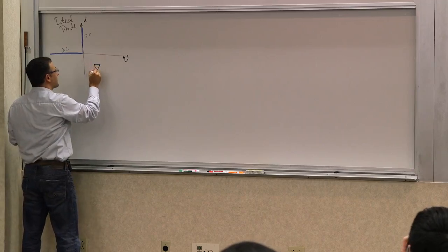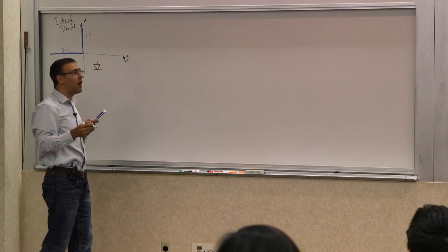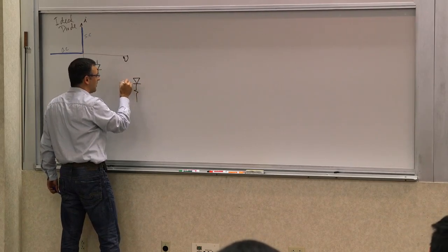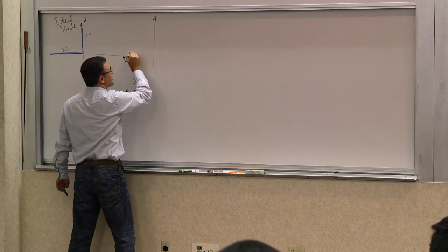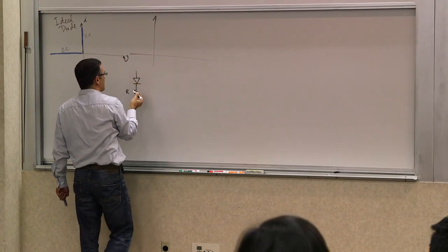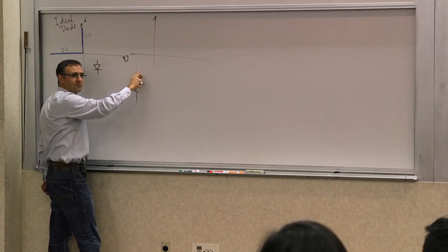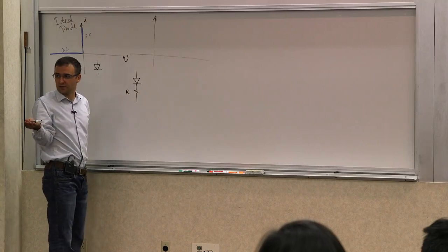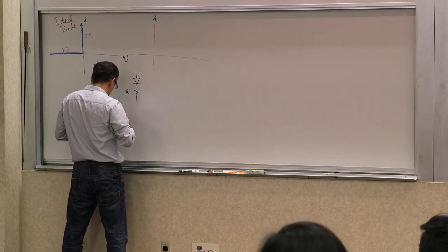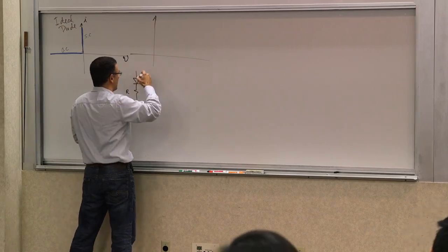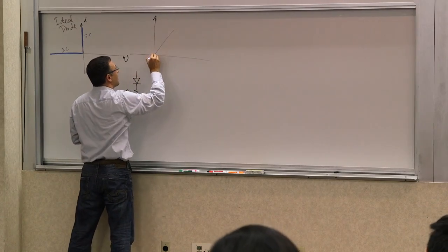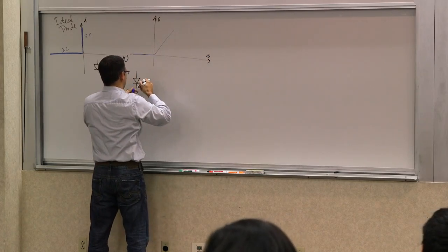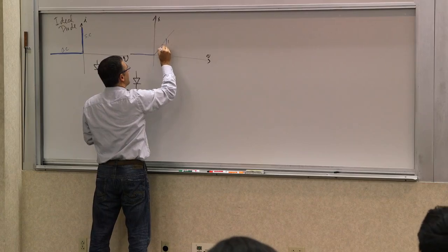We started building circuits with it, and we'll continue to do that. We also saw that if I add a resistor R in series with this, this curve will be adjusted. In the reverse it doesn't matter because it's an open circuit, an infinite resistance in series with a finite resistance, which is still an open circuit. But in the forward direction the diode becomes a short circuit, with a voltage drop across the resistor. So now the characteristic looks like this. This is the IV characteristic, I versus V, and the slope is 1 over R.